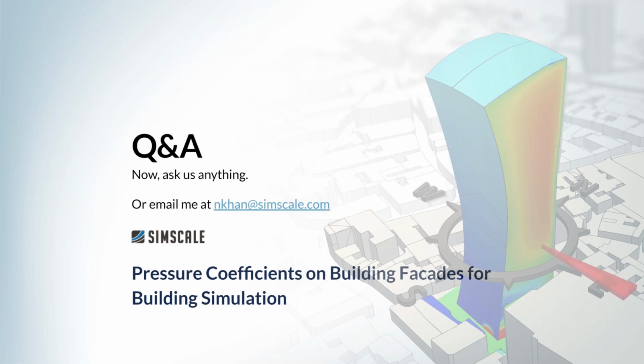It takes literally 2 to 3 minutes to set up a simulation, hit run, and you can choose how many wind directions you want to run it for. It could be 16, 12, 8, 4, 2, or even 1. Within minutes, you can start getting data out of it. On a previous project, a city center with I think 4 wind directions, we got results out in 15 minutes. Because it's transient, it's dynamic, you get some fantastic animations. You can see the airflow around the building, and a slice through that building as well. It's really great because you get the quantitative data too.